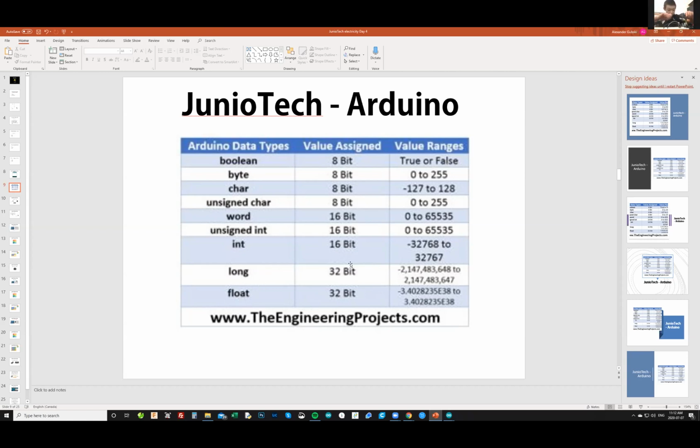And of course, if you want to save space, and for example, you know that your variable doesn't go past 100, you can use byte as a type of variable. So instead of int, you put byte, and this will allocate inside Arduino very little space for it, and you will save it for other things, right? Because sometimes you program a sketch that is doing all kinds of clever data manipulation, and then you have to manage how much data you can afford to allocate for any task. Anyway, we're using int because we don't care. That's the only variable in our code.